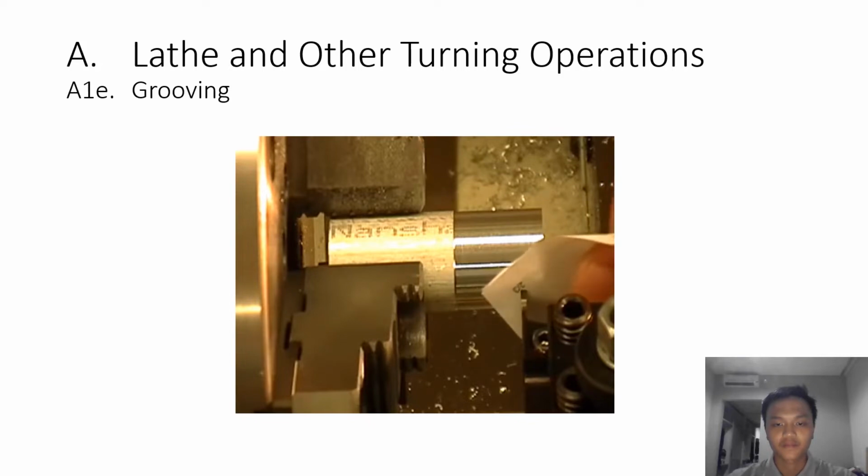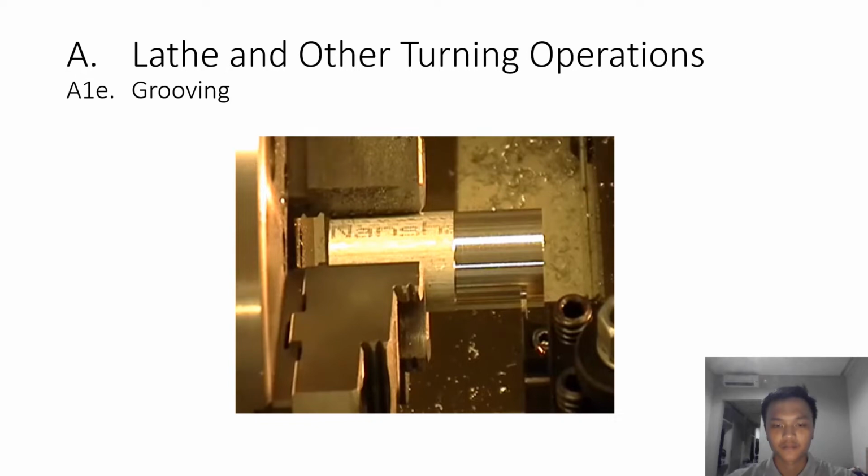Now the trick here with the X is a little different. Since we're actually cutting on a radius, we have to double the amount of that thickness. So I have to say that it's 0.008 bigger than whatever the diameter is. Okay, that's something you've got to remember.